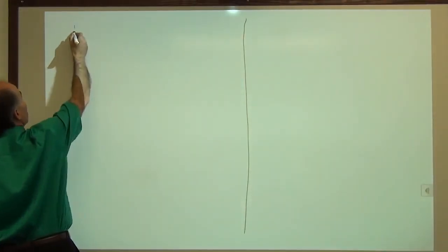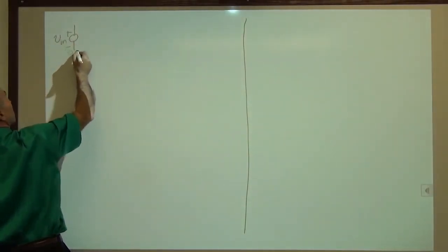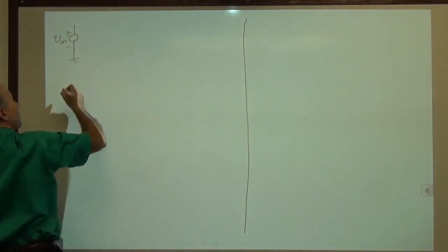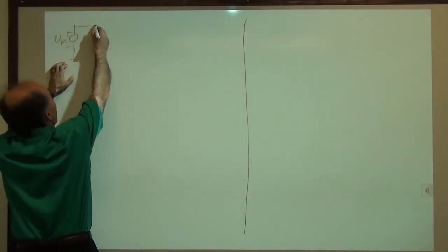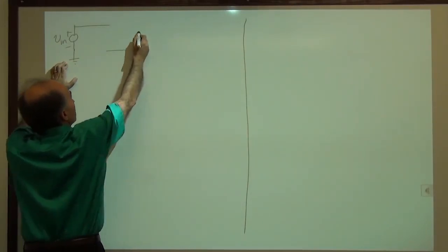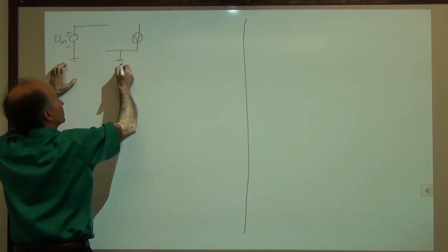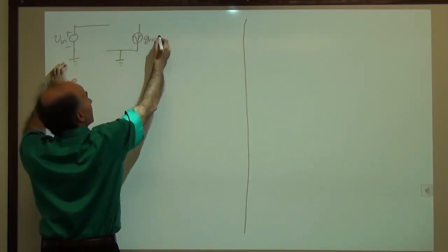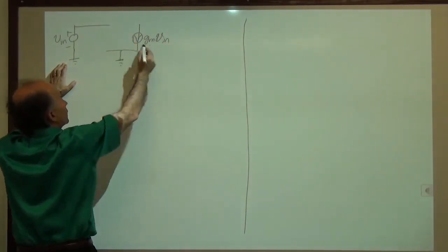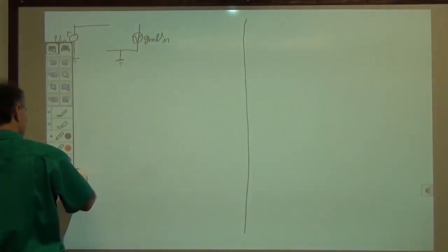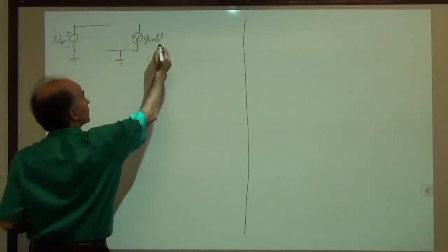All right, we begin with the microphone. So here's the microphone. We call it V in. It goes to ground because battery V0 is shorted out. Then we draw the small signal model of the device. So here's the small signal model of the device. The source is grounded also. And we have GM V1 to be precise. I'm just substituting the small signal model for the device.